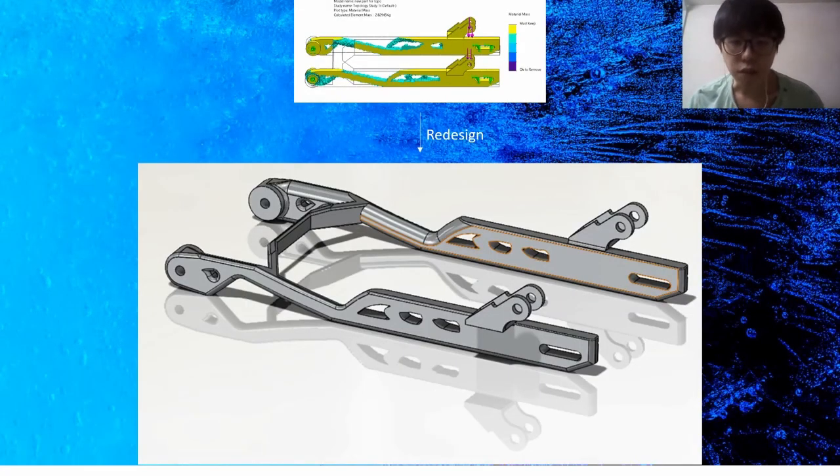Due to the safety factor after topology optimization, with 15% being less than 1, we changed the design of the swing arm a bit. The figure below shows the final design of the swing arm with a safety factor of 2.2 and mass reduction of 42% compared to the original swing arm.